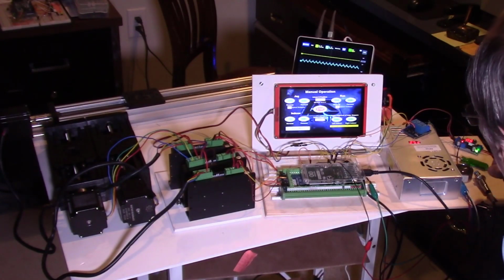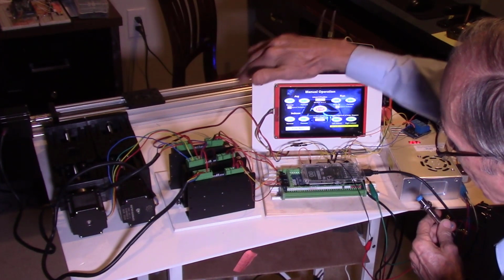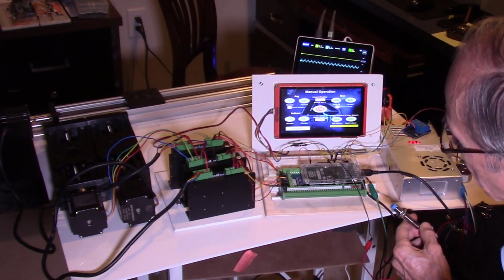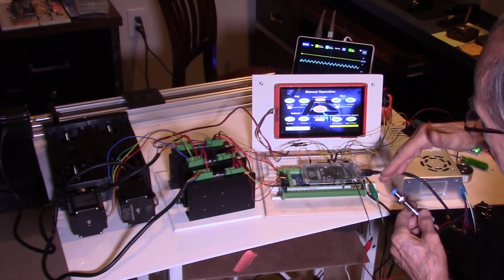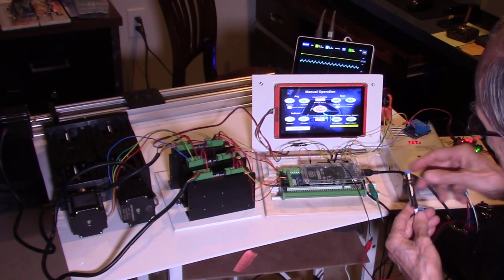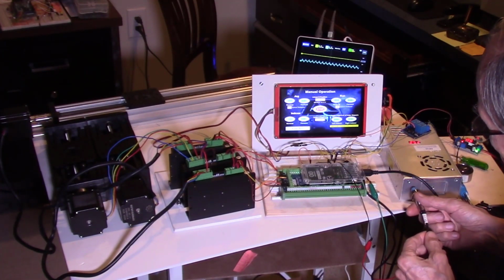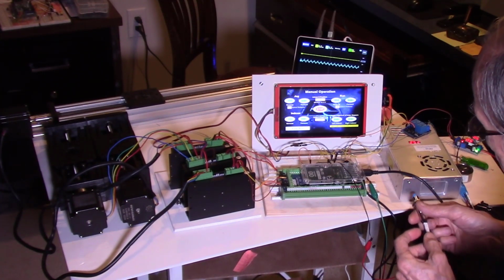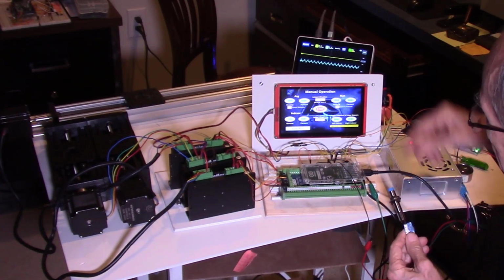The other feature we have is the Hall sensor. The way this works, if the travel on the linear X system exceeds the length of the rail, it'll hit this Hall sensor and then stop the program automatically. So this is the Hall sensor. It has a sensor here, so when it senses a magnetic field, it'll activate the system. You see that red LED went on. So I can actually show this.